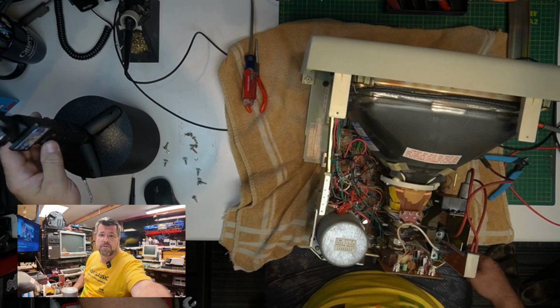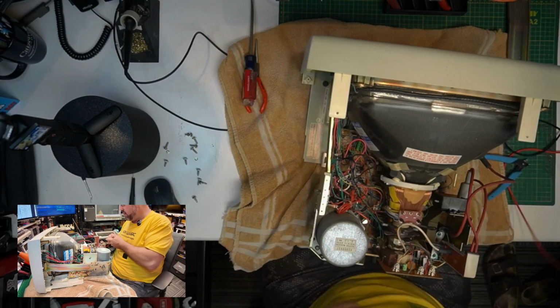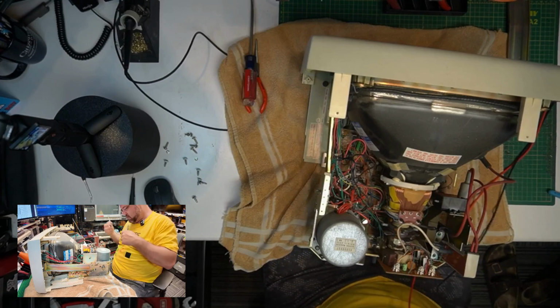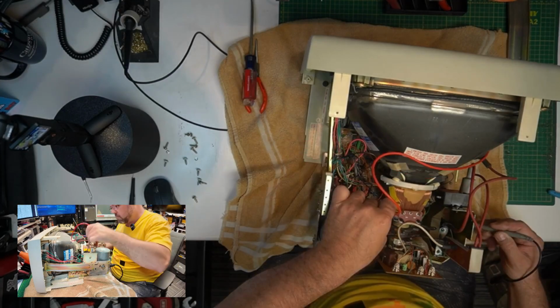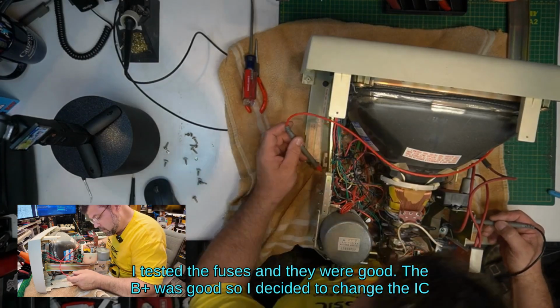Okay, so there is a fuse that looks like it might be for the B+. I'm going to go ahead and check that. Let's see how much voltage is on it. The fuse has 120 volts on it.